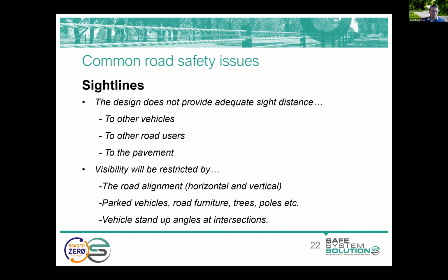It's desirable that the vehicle stands up at an angle as close to a right angle as possible, so that they have easy vision in both directions. You're not craning your head around and looking over your shoulder to try and see approaching vehicles. It's those Y intersections where there is quite an acute angle between traffic streams that we do see particularly high crash rates.